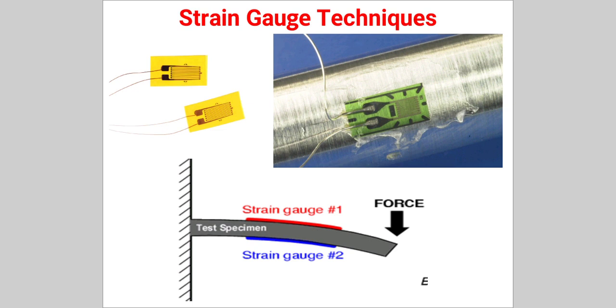unknown parameters. So these are the three techniques, that is photoelasticity, coating method, and strain gauge techniques, which are related to the ESA techniques. In comparison of these three techniques, as we have discussed, the concept of photoelasticity is applicable only for transparent materials, or only for photoelastic materials, which will be analyzed by using either a plane polariscopic device or a reflection polariscopic device, which is also called a quantitative method.